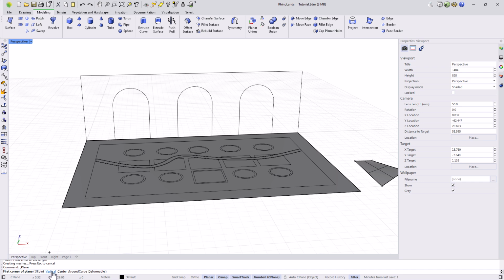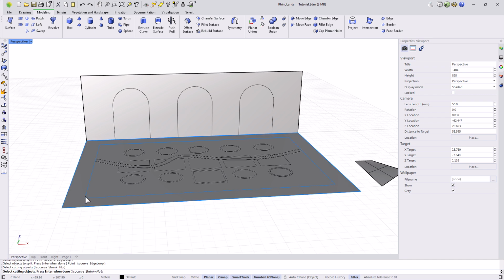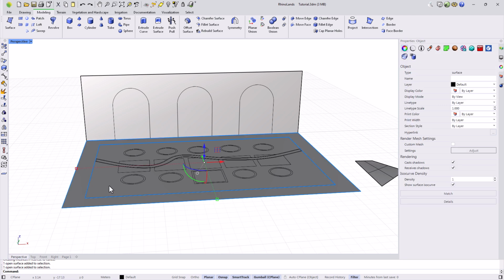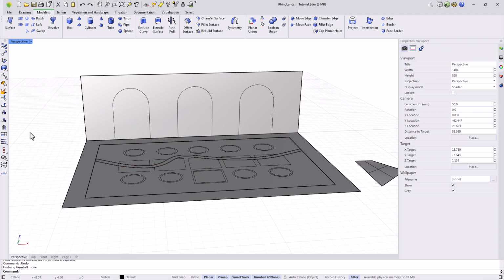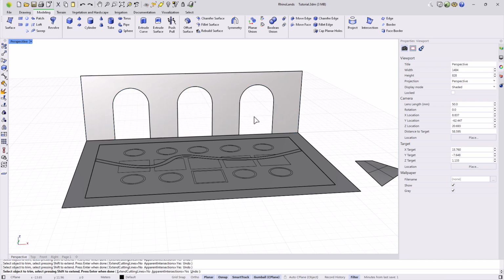With the corner-to-corner plane, we also have the option to select vertical plane. And first we define an axis, and finally its height. Surfaces can also be transformed using the tools from the sidebar, such as moving, scaling, grouping, or splitting. For example, with the subdivide command, we can select the surface we've created, select the inner curve, and in this way have 2 distinct surfaces, allowing us to apply different thicknesses or materials. And with trimming, we can use outlines to remove parts of this surface.